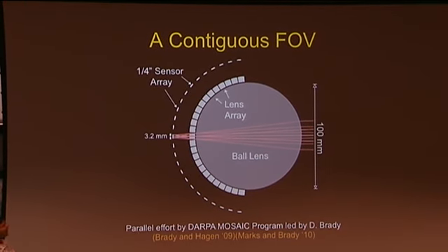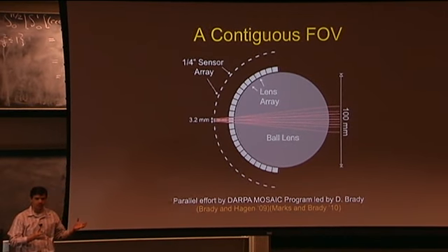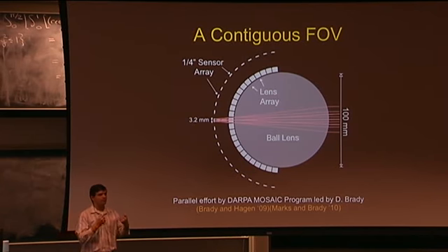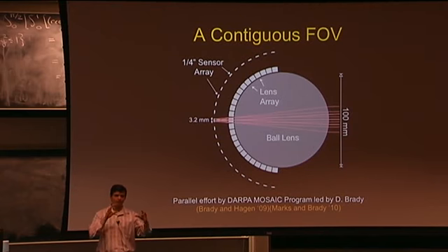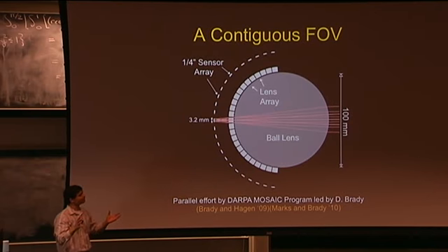But the previous design had one slight problem, which is really a practical issue: when you try to pack these sensors really close together, you run into issues. Basically, you can't get the active area of each sensor to be perfectly abutting. There's no practical way to do that. So one way you can get around the issue is to create multiple systems with slight shifts in orientation, and that allows you to fully cover the field of view.